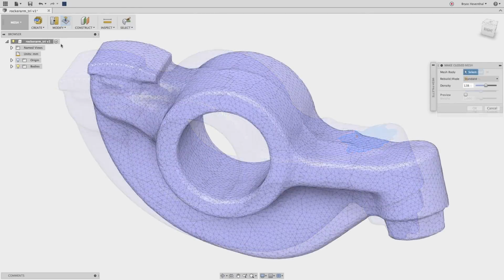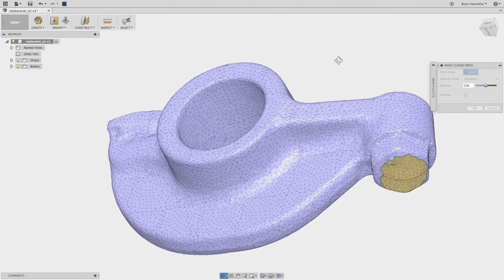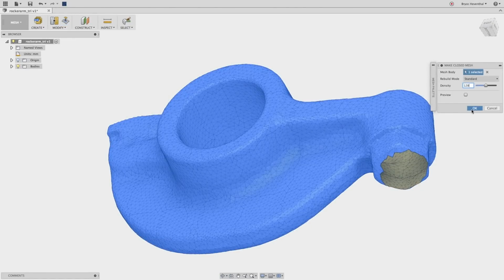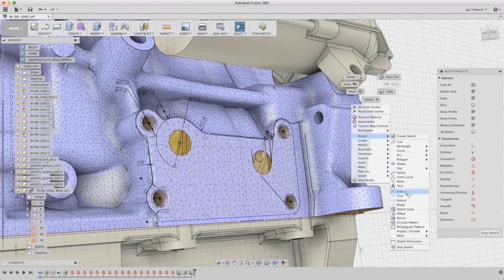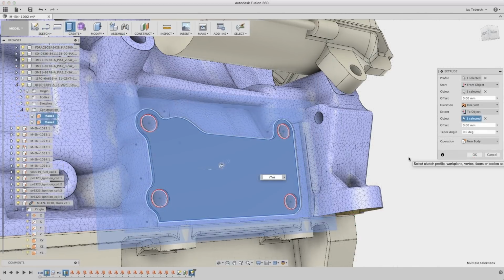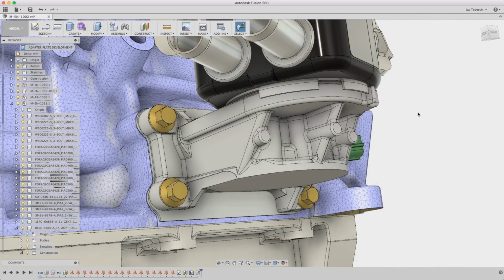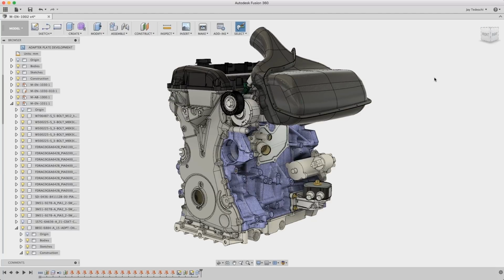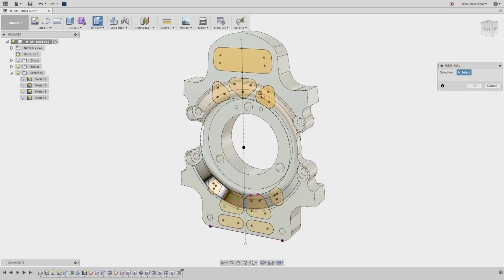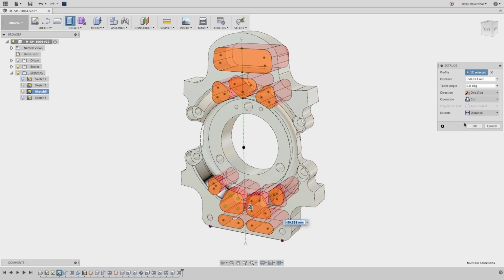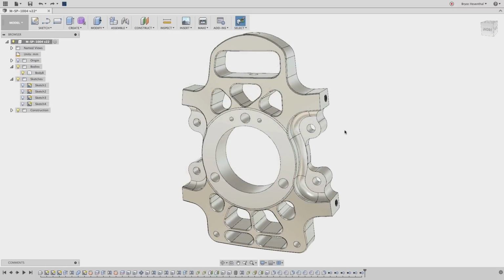Finally, let's edit and repair mesh files right inside our CAD tool. Take STLs or OBJs from your scanner or other CAD tool and edit them right inside the same package as your engineering tools. Use this mesh to make a sketch cross-section, and now we can add parametric features right to that design. Fusion 360 gives you the flexibility to choose your preferred modeling method when it's most convenient in your product development process. Even combine them to get some really slick workflows.